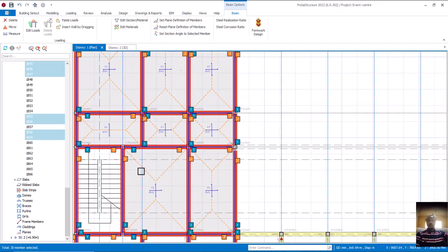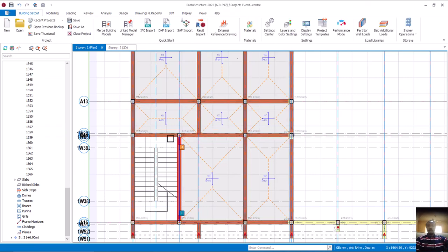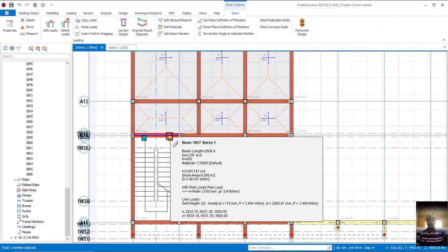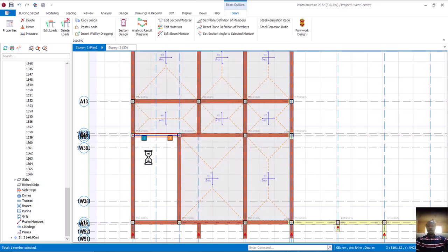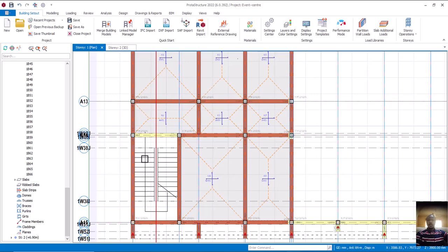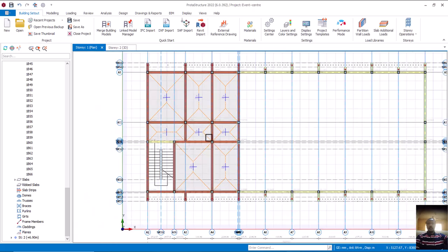But if you look at this place now, this is the place where people are going to pass. So I can't block this place. So automatically I'll remove this wall load. Is that okay? It's not going to have a wall load. So delete wall load, delete load. Okay, I'll click on okay. All right, for easy access, I'm not going to block this place. All right, that's fine.